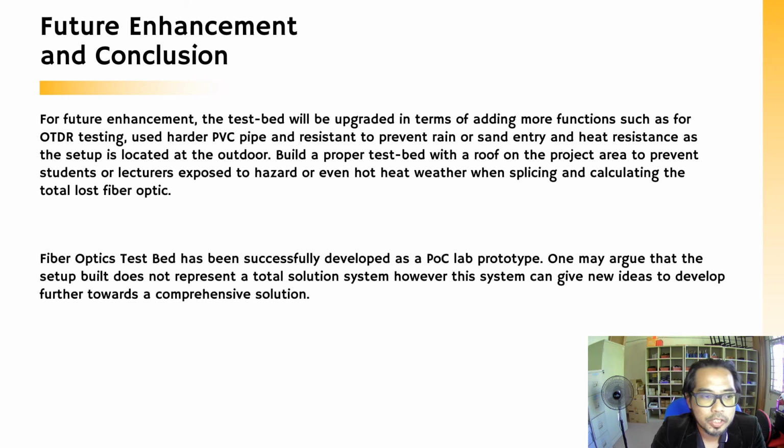For the future enhancement, the test bed will be upgraded in terms of adding more functions, such as OTDR testing. Use harder PVC pipe that is resistant to rain or sand entry and heat, as the setup is located outdoors. Build a proper test bed with a roof on the project area to prevent students or lecturers from being exposed to hazards or even hot weather when splicing and calculating the total loss of fiber optics.